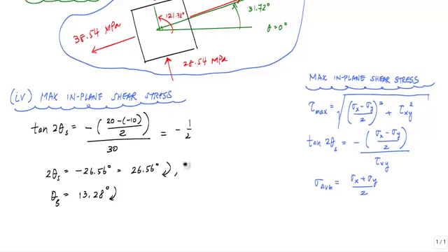There is a solution 180 degrees from -26.56 degrees. If I add 180 to it, I would have 153.44 degrees, and this would be the direction going counterclockwise. And here, this would also be divided by 2, would be 76.72 degrees going counterclockwise. But the reality is, in this problem, you only need one angle because the shear stresses on each side are the same.